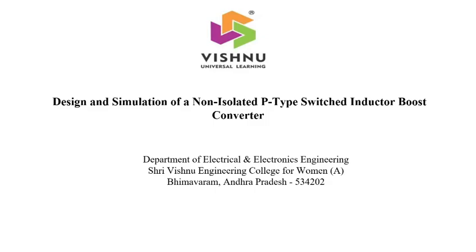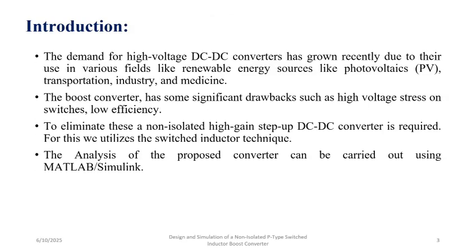Good morning. Our title is Design and Simulation of a Non-Isolated P-type Switched Inductor Boost Converter. The main aim of the project is to design a switched inductor boost converter to obtain a high voltage gain at a lower duty ratio. The conventional boost converter has some significant drawbacks, such as high voltage stress on switches and low efficiency. The analysis of the proposed converter can be carried out using MATLAB or Simulink.